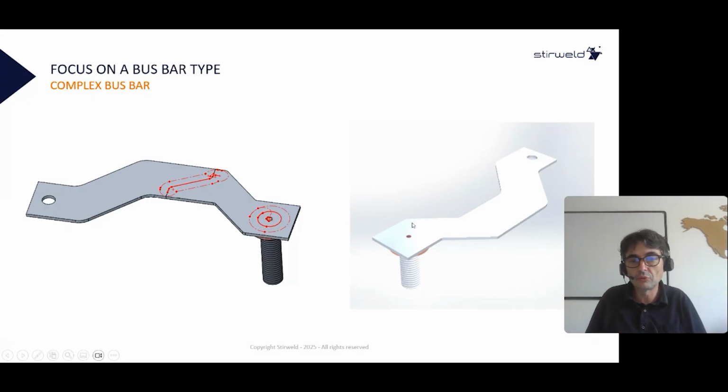For that we use a circular lap weld to go through this flat sheet and start to weld the axis under the plate. So that is very common. Now by friction stir welding it's also possible to weld together the two sheets here. And that is very interesting because as we have a complex geometry here, we must start from a square rectangular sheet.